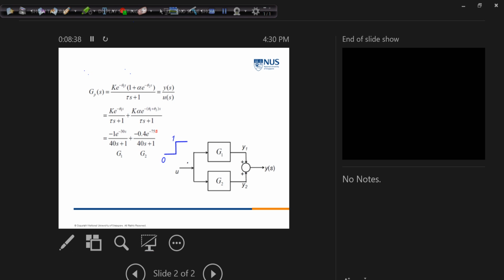If you consider the block diagram, which we will commonly use for control system design, this has no controller, so this is like an open loop system. We only consider how the system reacts to the input. Although it's two parts, if you turn this into a Simulink-understandable block diagram, we have the U input, and then this is a summation.